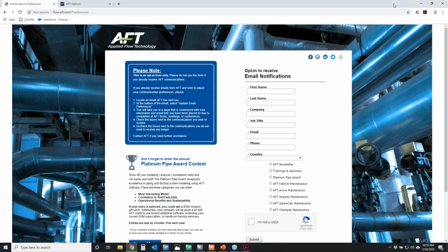It's because you want to focus on the piping itself that's connected to your relief valves. And you also want to be able to identify how your relief valves are going to impact your overall system performance. If you have relief valves popping open and you've got flow through them, what's that doing to the flows and pressure distributions in the rest of your system? Do you have other issues that are materializing?